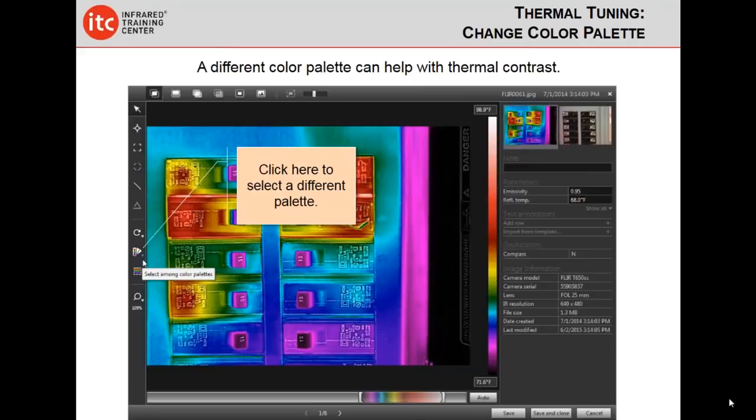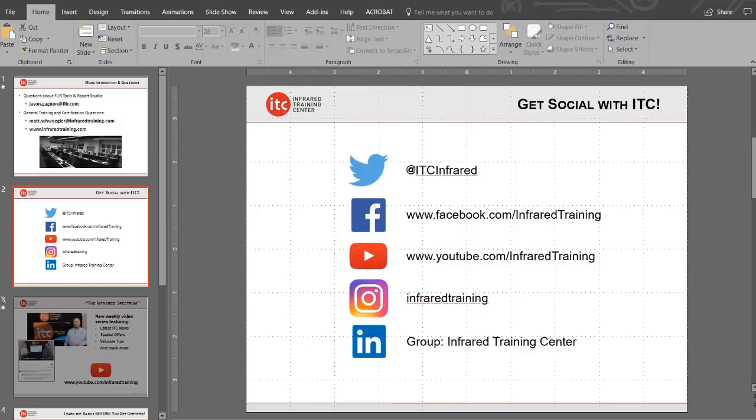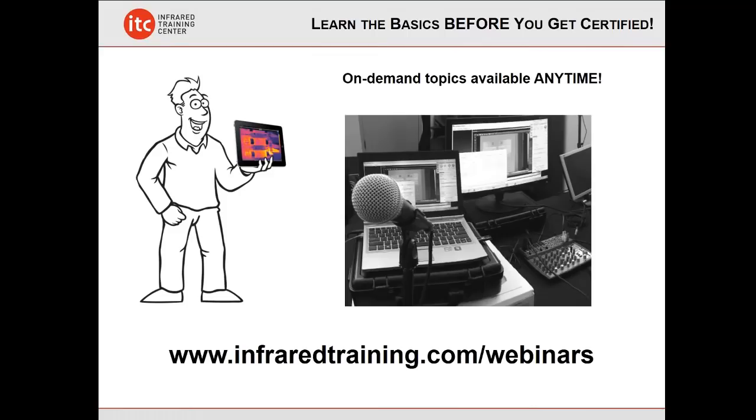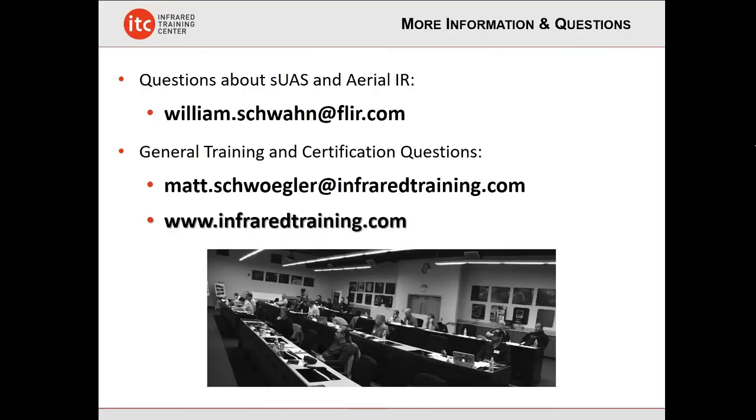Okay. Maybe you can speak briefly for a moment about radiometric versus non-radiometric solutions for aerial inspections. When would you use one versus the other? For someone getting into this, why would they care about either one? Absolutely, non-radiometric. I'm going to fly the roof, and I'm going to do what's called a qualitative inspection. So flying a roof membrane to look for thermal patterns of where moisture might be, where structural, or where nailings are, is qualitative. So we might not need or require a radiometric camera for that version.